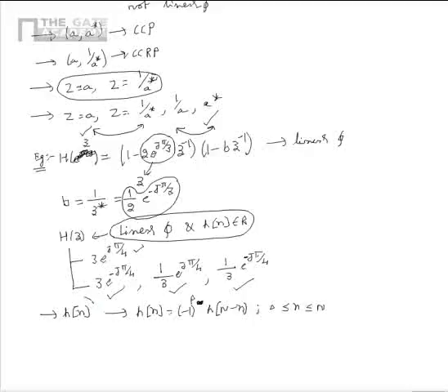So it's given that there is an LTI system of impulse response h(n) which satisfies the relation h(n) equal to minus 1 whole power p h(N minus n), where 0 is less than or equal to n is less than or equal to N, depending on the case that p is equal to 0 or 1, that is, the sign is positive or negative, and depending on the case that N is even or odd.